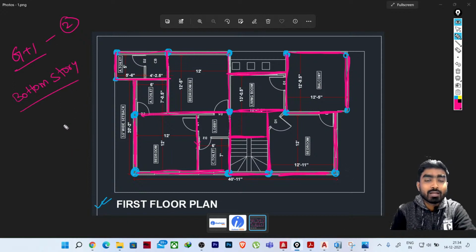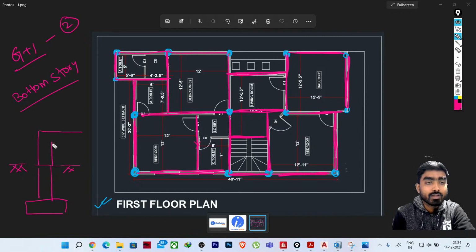Now, in such cases, what we used to have, like if you have a basement, that is different. If you have such cases, very small structures and this kind of scenario, how we used to provide the beams first, like if you see, this foundation, then column, maybe here we have the ground level, then the column will go up to the plinth level. Here we will have the plinth level. Obviously this column will be continued, we just delete this. It will be continued like this. Then we will have the first floor. So this is my plinth level.